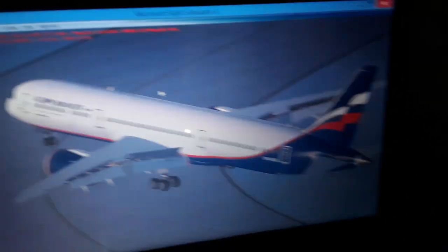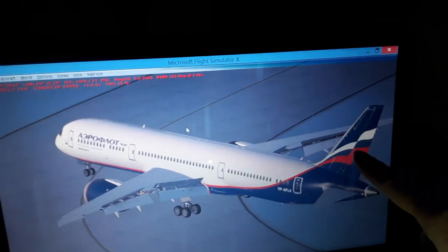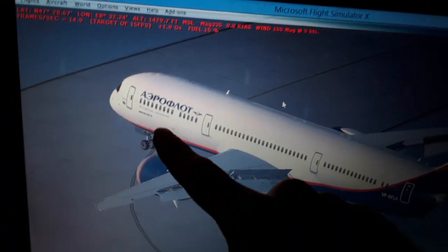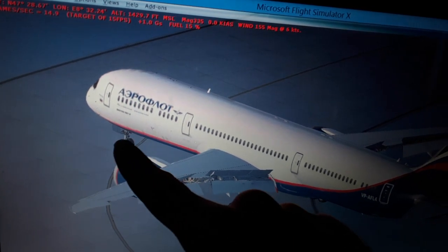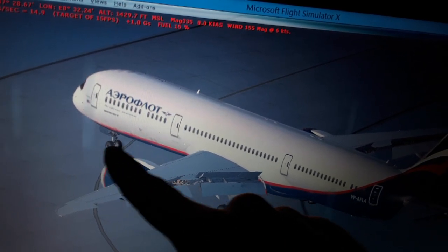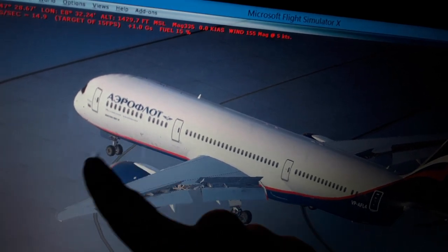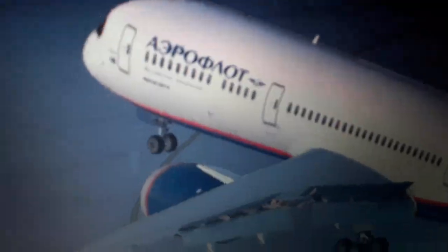Also we have the nose wheel for the ground maneuvers for takeoff and for landing, to make left and right turns alongside with the rudder, depending on the airspeed of the aircraft. From an airspeed of 0 to about 45 knots, like 70 kilometers an hour, we have a deflection of about 76 degrees either left or right for the forward nose wheel of the aircraft.